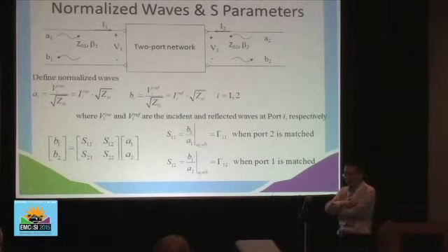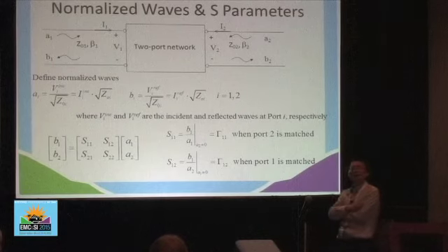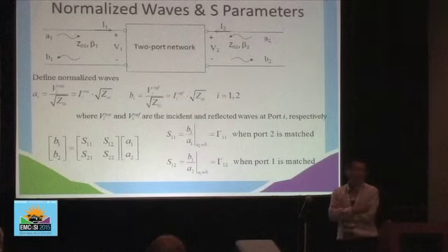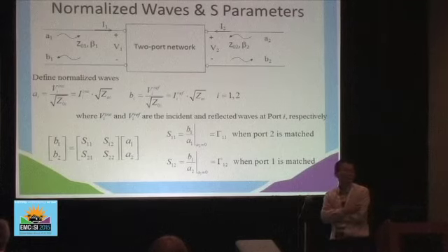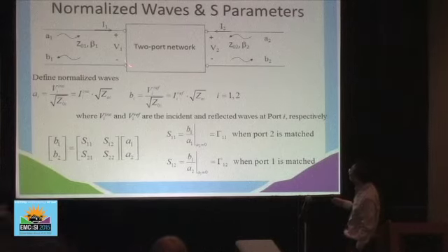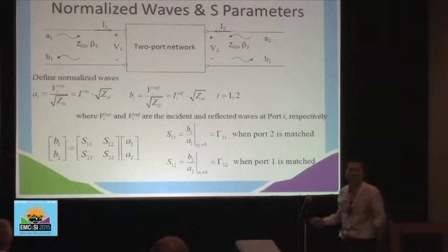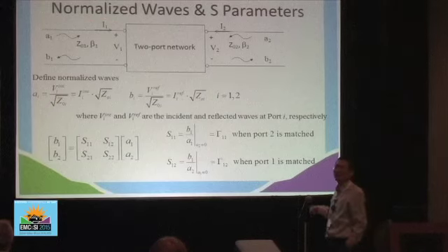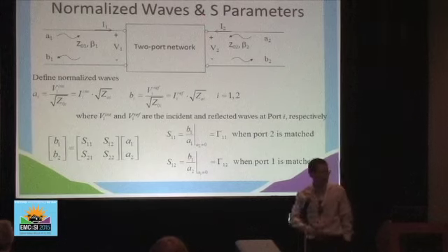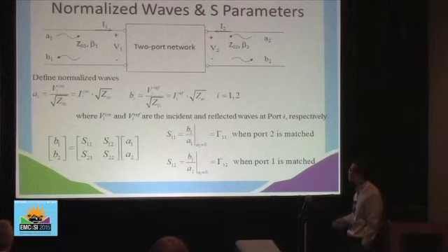All right, so when we have this transmission line concept, then we can further derive a little bit to understand the scattering parameters. It's very useful at the high frequencies to describe the behaviors of a geometry. So if we have something, a black box, we don't know what's inside of the black box. We're trying to describe the behavior of this black box. One way to do it is to relate the terminal behaviors together to describe the behavior of this network. That's called the network analysis.